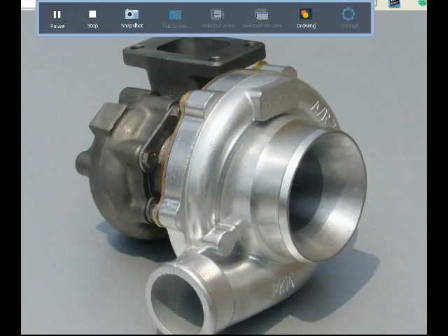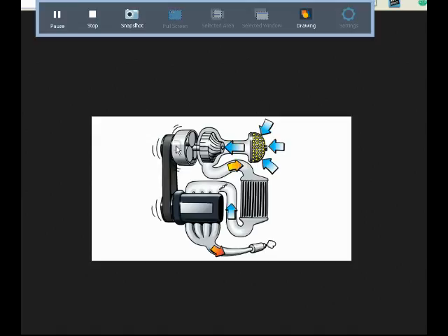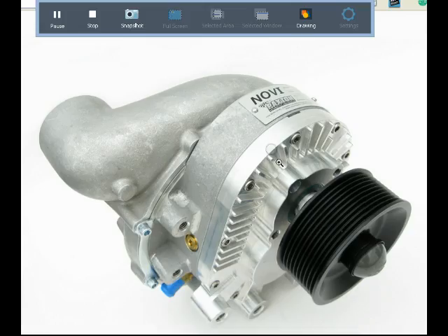As for the supercharger, same thing, except no turbine, and the centrifugal flow air compressor is driven by the engine itself through a belt. Same thing, and you're going to have some regulation so it doesn't over or under boost. And then here's a picture of one. No turbine there, remember, it's got a belt drive, and then you got the centrifugal flow compressor. It draws in air from the other side inward, slings it through the diffuser and sends it out to the engine. So you can get away with a supercharger at lower altitudes, of course. But, you know, there is a pro and con to everything, right?